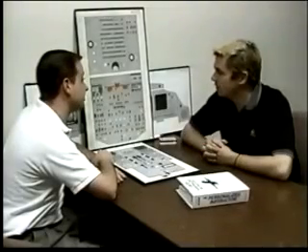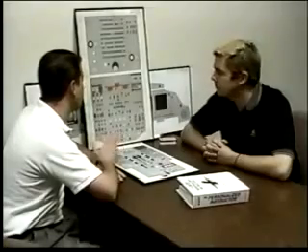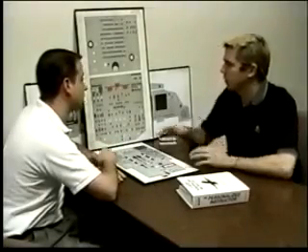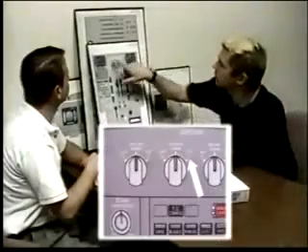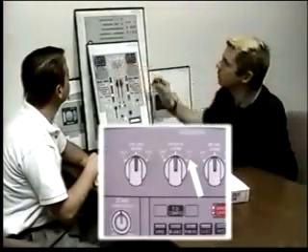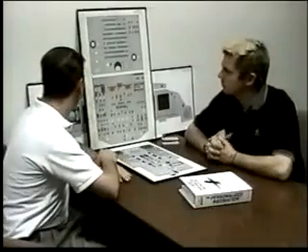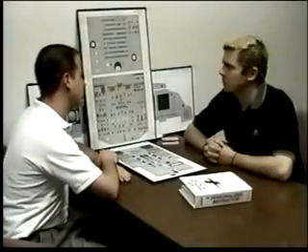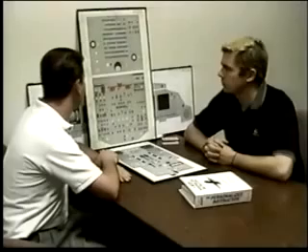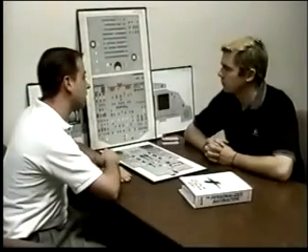That ADR 2 is failed. How would you get that information back to the first officer? On this panel, I would select air data, first officer on 3. You told me that with a flashing fault light on IR1, the attitude heading information may be recoverable. Where would you find that procedure, and how would you recover the information?